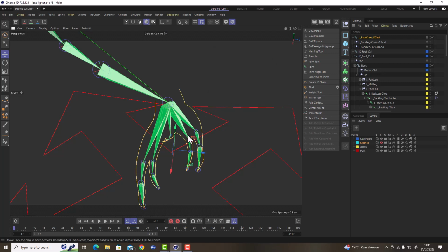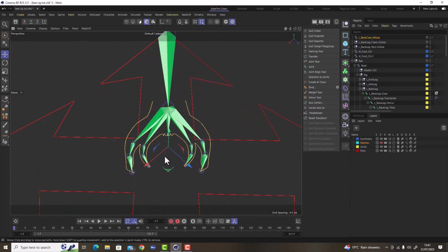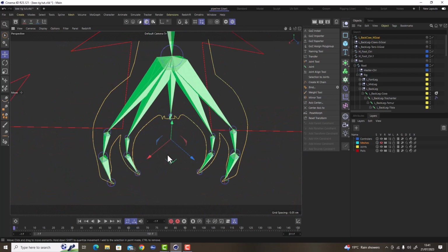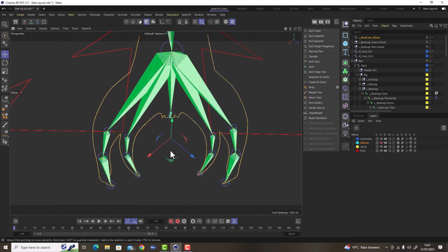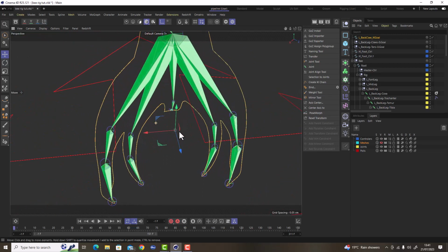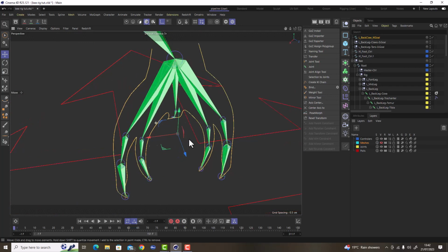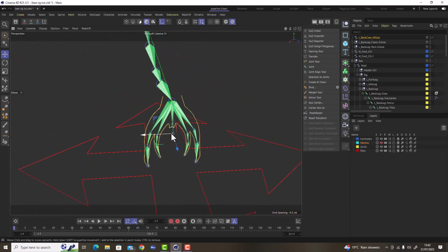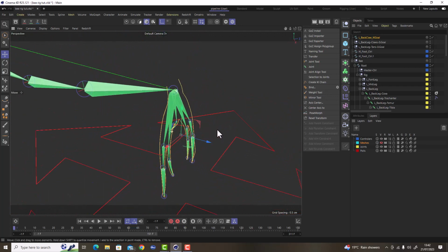And when I've done that, you can see here that the controller is actually 45 degrees out from where it should be. So this is an easier fix, of course. We go to our axis, we will rotate it with the shift key held down once we've started that movement to 45 degrees, and now you can see that's exactly the way that it should be. That's perfect.